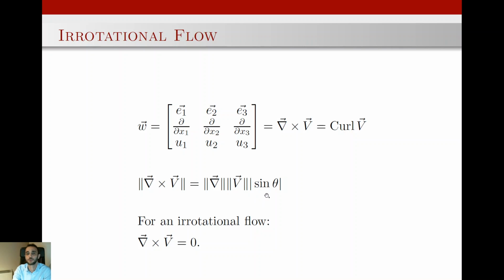Notice that this is a pure mathematical description of a physical phenomenon. So there is no physical meaning for this vector, but mathematically we can write it this way. Now, if we assume that the flow is irrotational, that is, we eliminate one of the other motions that I discussed earlier, then curl of velocity is going to be 0.